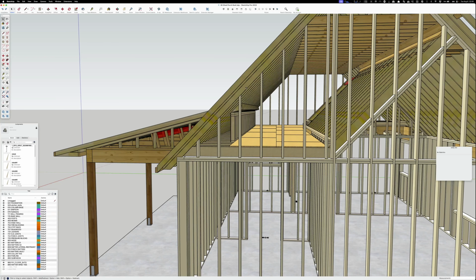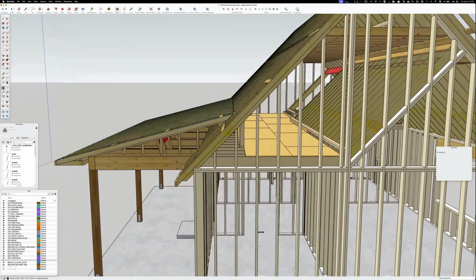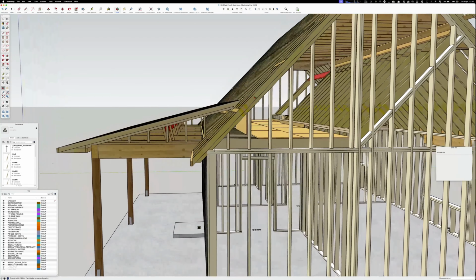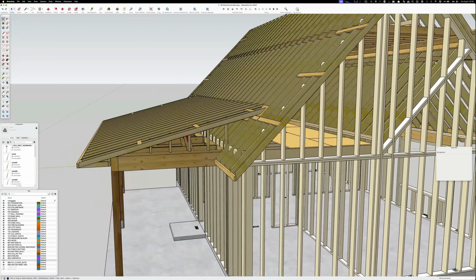You just need to nail the rafters to a 2x8 or a 2x10 on the layout that they're supposed to be, and that will make them all even in plane with each other. They'll be straight across here. Then, once that's done, you don't have to do the calculation. You could probably just eyeball this, put a level on here. You could play that game.